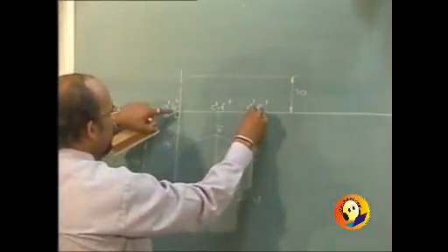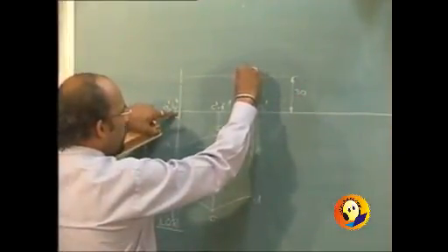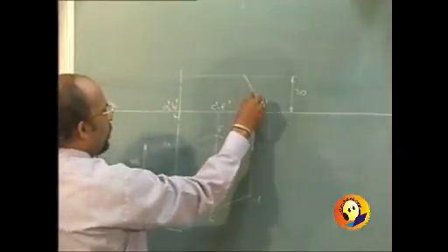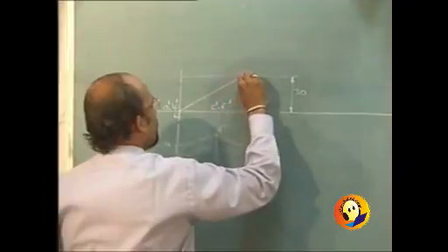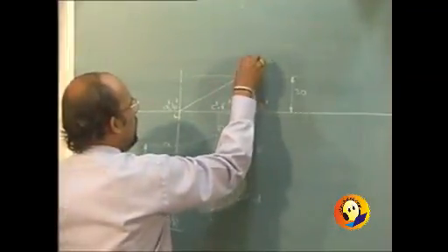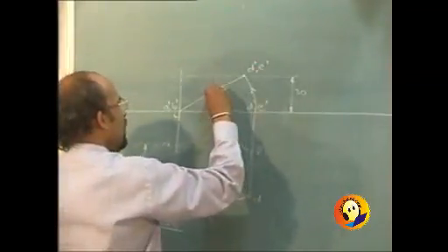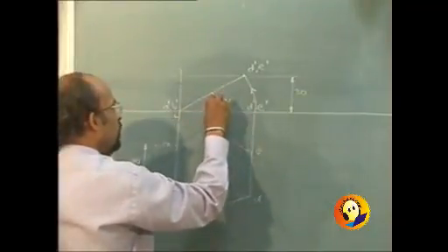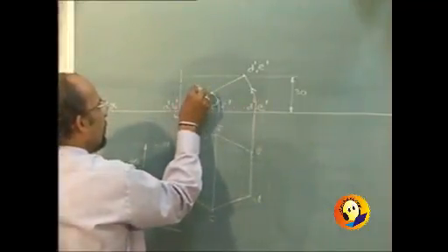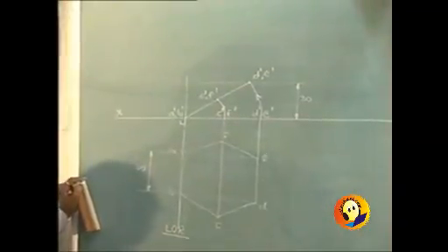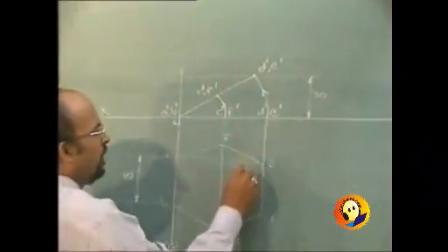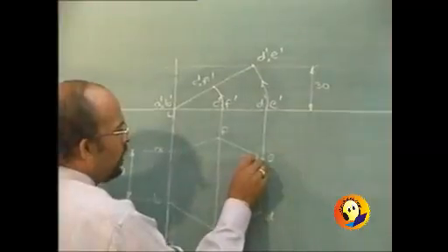and then using the compass you can rotate and join this. This will be the final point D dash E dash, and also C dash F dash are to be rotated and marked. As per our rules, rotation in one view is movement parallel to XY in the other.